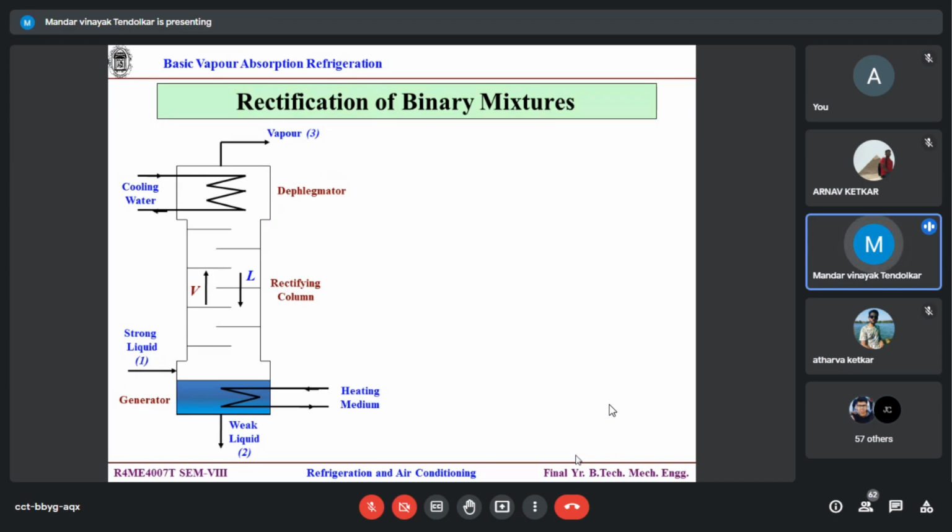Okay, so instead of wasting the space in the horizontal manner by adding different heat exchangers, I'm adding it in the vertical sense. So that way I can save the space and I'm getting the effect of the density difference. Vapor will go in the upward direction, liquid will fall in the downward direction. Plus gravity. So wastage of space reduced, material reduced. I need not have different heat exchangers. It's simple plates. So material wastage reduced, space reduced, time reduced, cleaning, maintenance, overhauling, everything reduced.